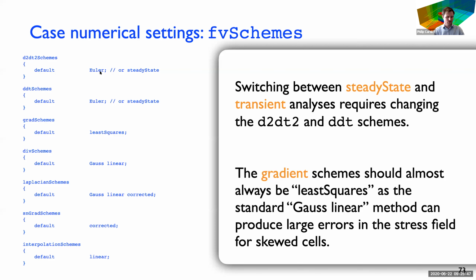And there isn't one included by default, even though I know quite a few people have been asking about it. So eventually someone will implement it and push it in. I guess I could do it if I have time at some point. So Euler is fine. If you have a transient case with waving and bouncing, you might get a lot of energy dissipation with Euler, just first order. Of course, there are explicit solvers implemented as well, in which case the time step's so small it doesn't really matter if you're using Euler.